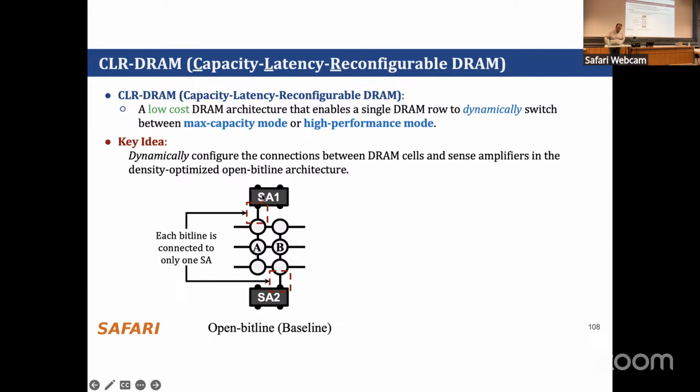And the original data of another bitline is also connected here, and that goes to another subarray. So once you activate some row in a subarray here, you're going to have the NOT of your data in this bitline in your lower subarray as well. So with that architecture, you can implement NOT.